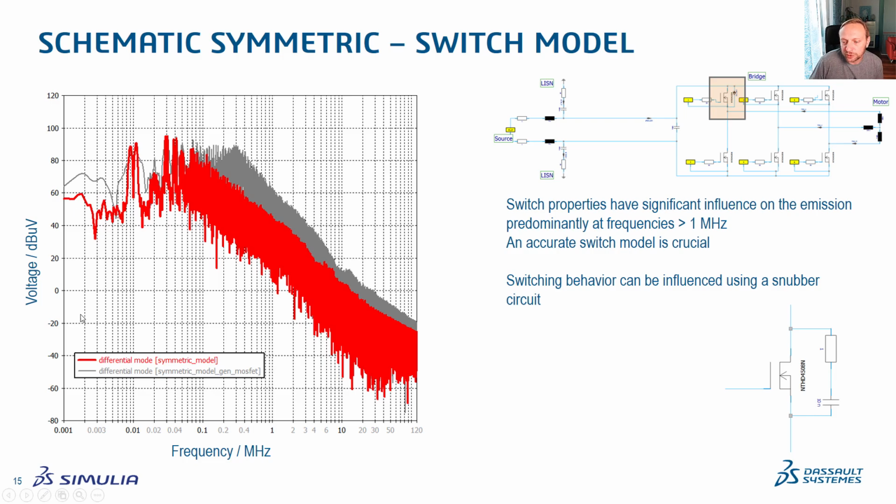One first thing you might do when we talk about EMC, before going to the step of filtering, is to apply a so-called snubber circuit. You can see here a so-called RC snubber circuit. I have a resistor and a capacitor between gate and source of the transistor, and it can dampen or improve your EMC emission simply because you create a path for this higher frequency behavior, right?